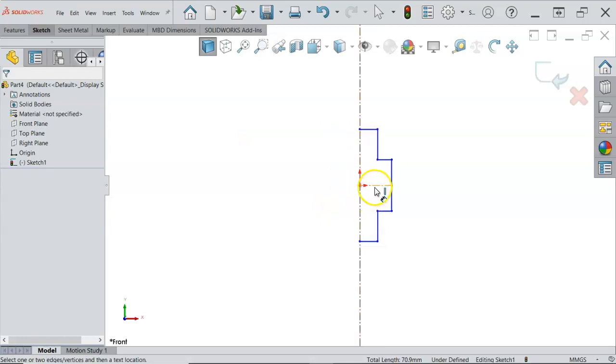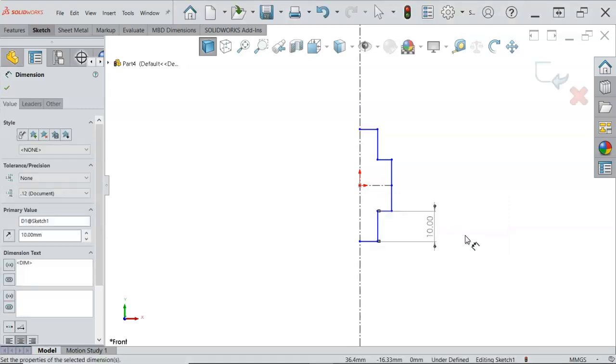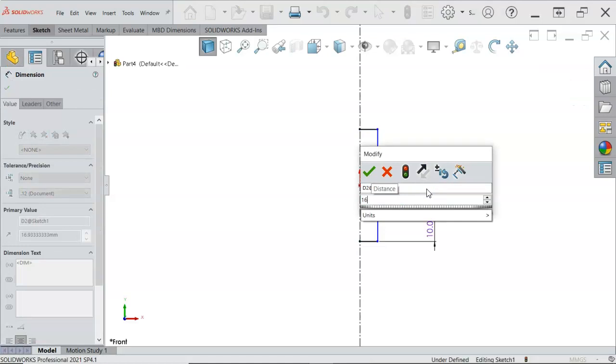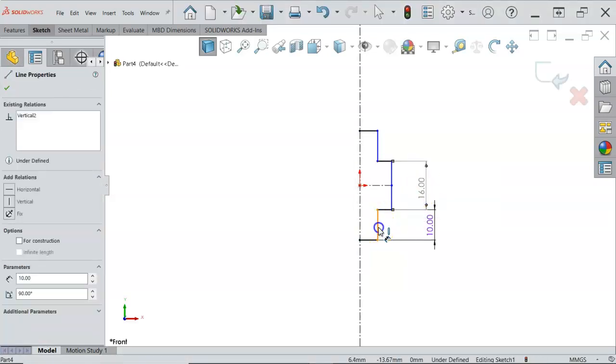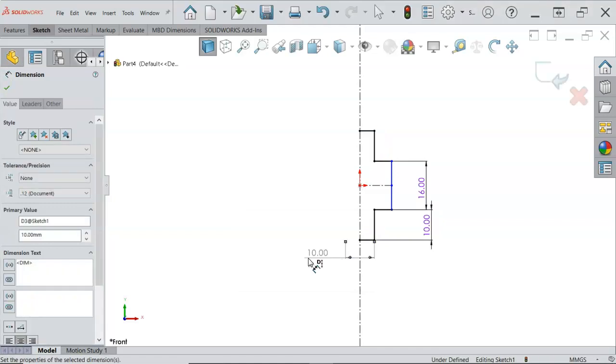All right, so that second center line is going to kind of confuse the revolve. So I will need to still set the axis of revolution when I get to that point. So 10, 16, and our diameters are, and I want to make sure to pick the center line. Well, I didn't put any object line in the middle there, so we have 10 for the diameter.